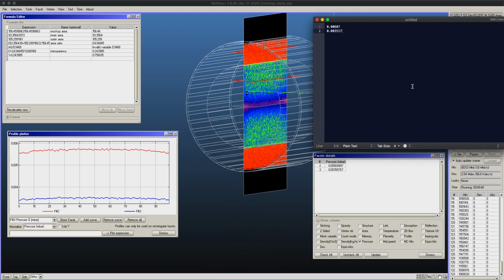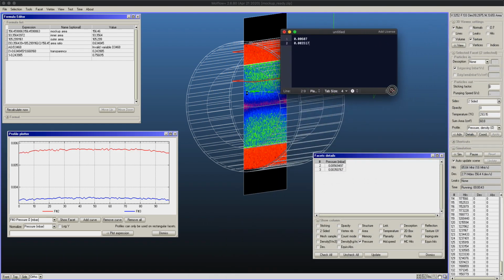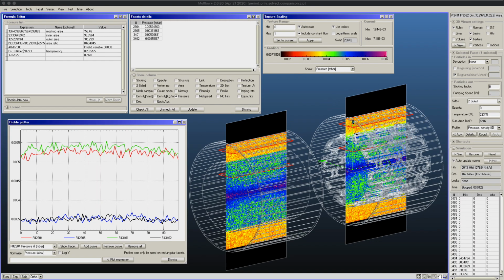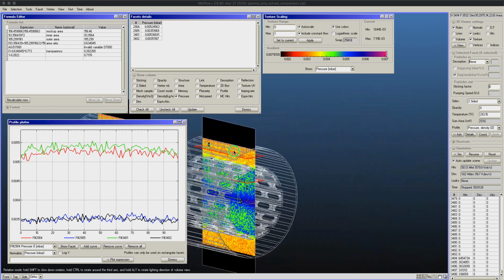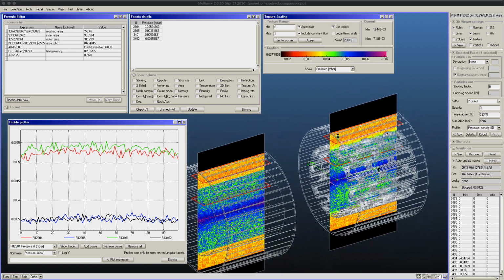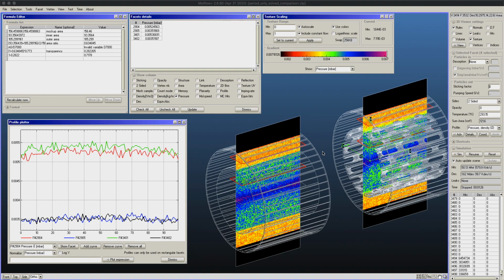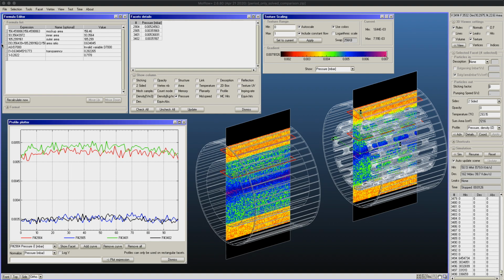And then, here is the notes that I've taken at the beginning of this tutorial. Okay, I'll do some updates. So I did the comparison. I was actually importing the two geometries to be next to each other. So here you can see the original geometry, and here the one which is simplified. The only thing is that I slightly updated the values calculated before here in the formula editor because of the issue before. When I calculated the transmission ratio of the hole, I accidentally selected uniform desorption as opposed to the cosine desorption, which should be the default for vacuum systems.